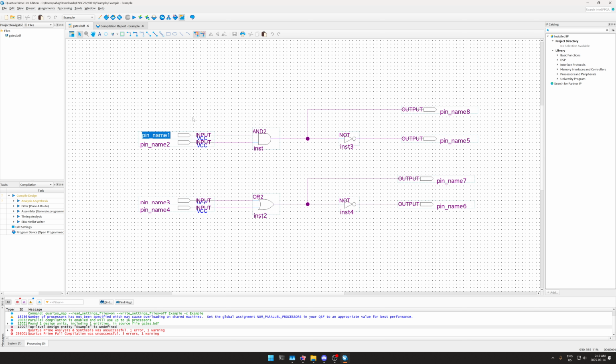The reason I like this so much is I'm going to go ahead and name it and_input1 and press enter, which takes me down to the next input. So we're going to do this for all. Now, the reason I'm using _input or any such extensions is because by default, if I were to say and or use NAND, the simulation or synthesis would disagree.